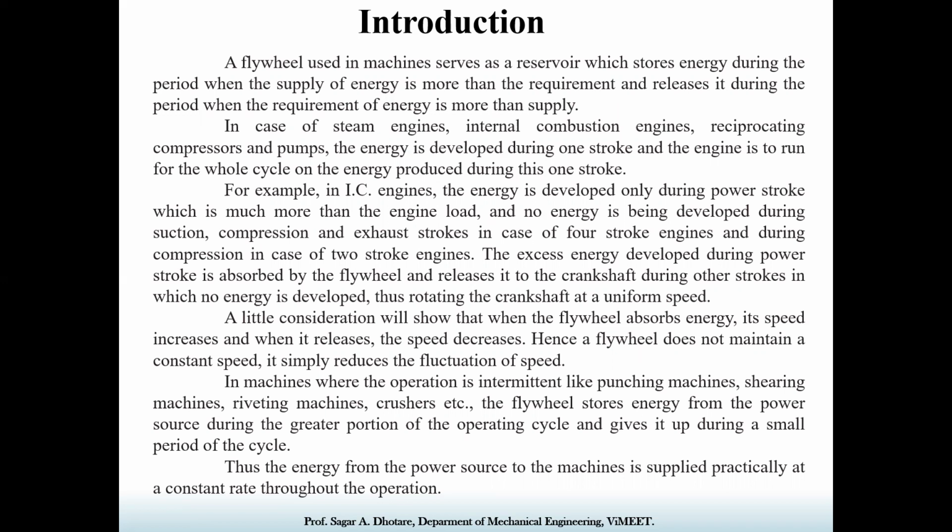So in a four-stroke engine, generally the power stroke creates the energy. At that time, the excessive energy is generated, which is stored in the flywheel, and that energy can return to the engine for completion of the remaining three strokes, that is suction, compression, and exhaust.